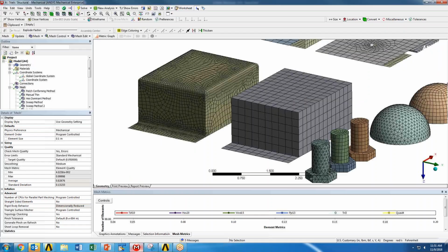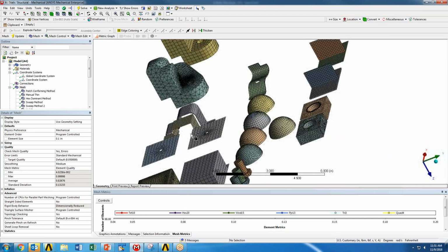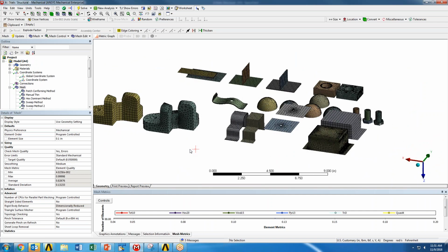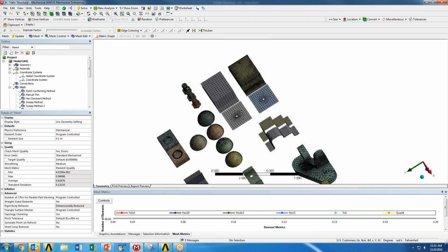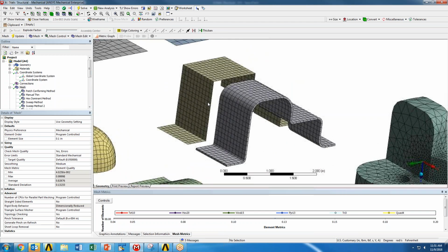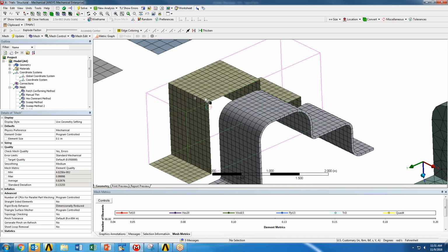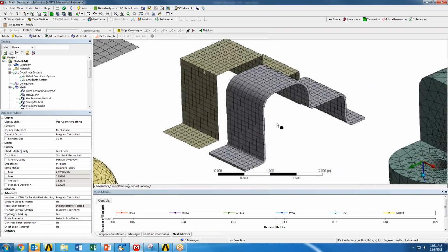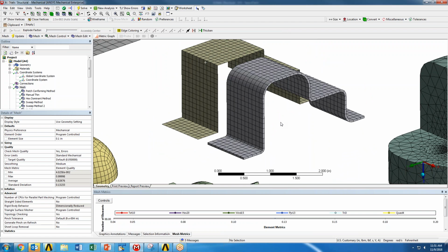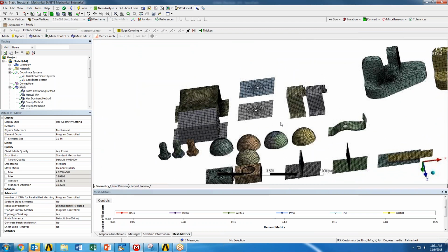From the perspective of meshing those things, the final body here is going to be very smoothly, uniformly meshed. We could mesh with solids, but generally for solid elements, depending on the stress or the deflection you're seeing, you usually want more than 1 element through the thickness. If you're experiencing only bending, then 1 element through the thickness is acceptable, but that is almost never the case. So you usually want at least 2 elements through the thickness, if not more.